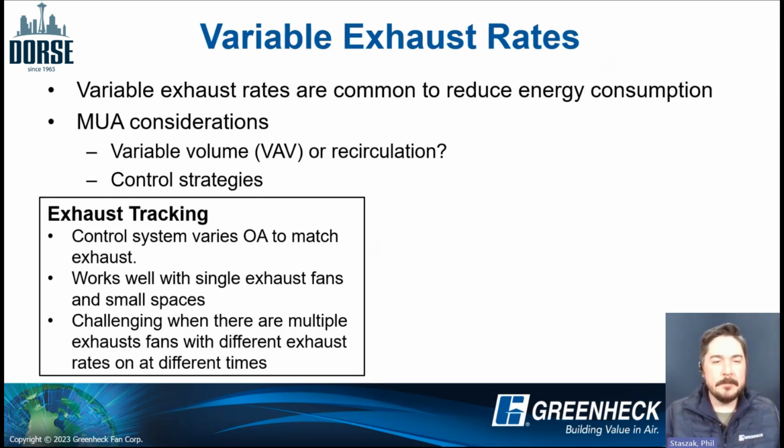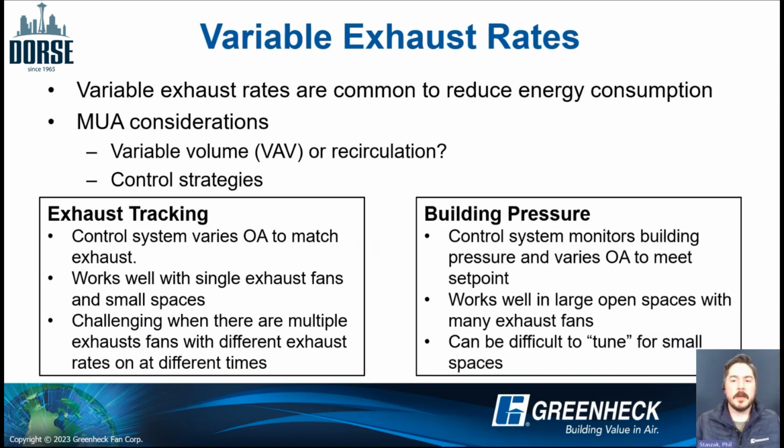So exhaust tracking, very common with single exhaust fan type systems, where we're looking at just tracking: if this exhaust fan is on, or if this exhaust fan is running at this speed, the supply fan will run at the same, typically for a more one-on-one type scenario.